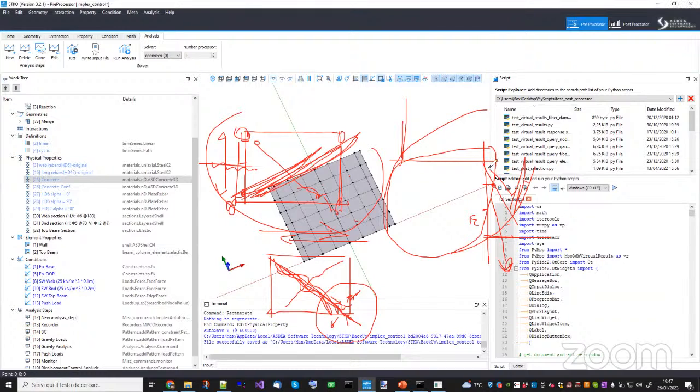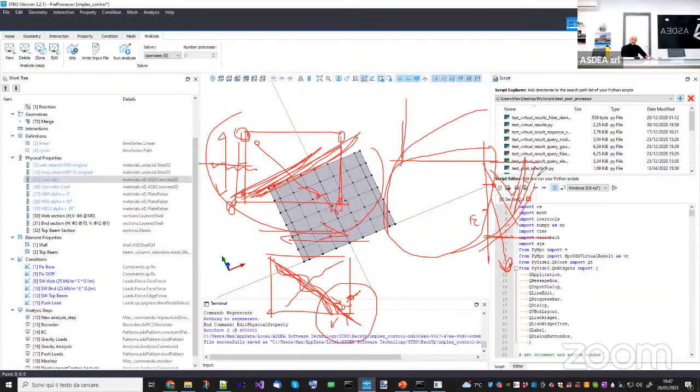Before, I see. And before, the problem was that the tensile surface was active up to this point, okay? So if you are in pure tension, the tensile surface was not active. But as soon as you move a little bit into tension-compression, even if the compression was a very small portion, it was activating the entire surface. That's why it was reducing the entire domain a lot.